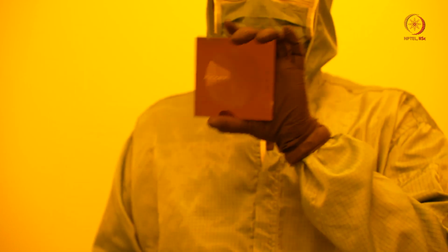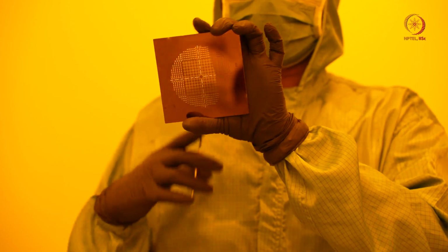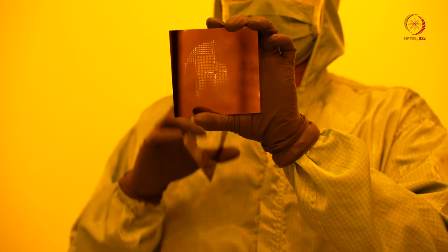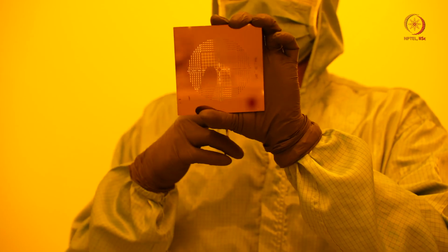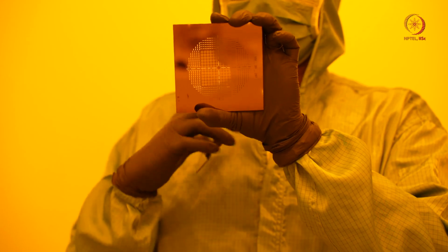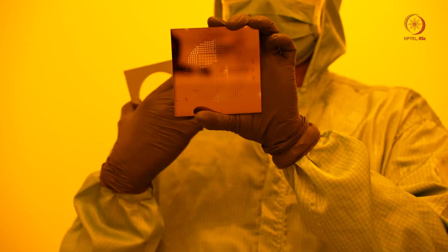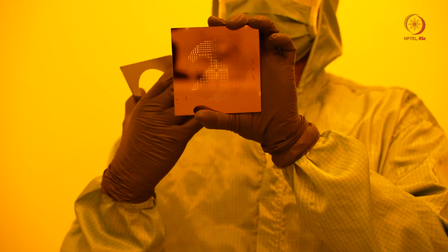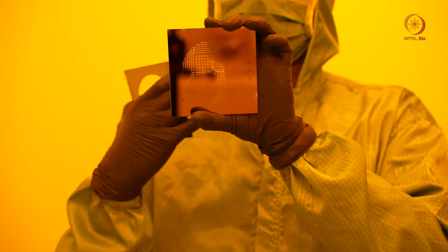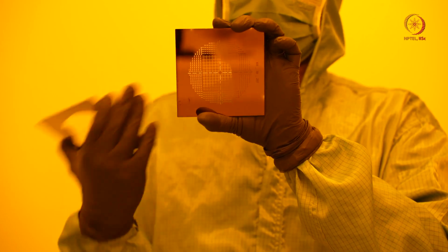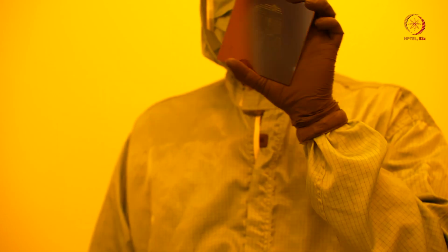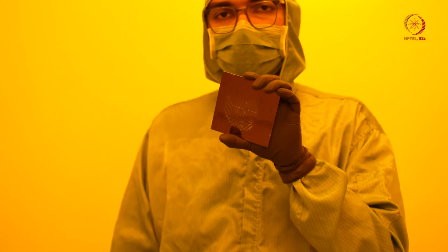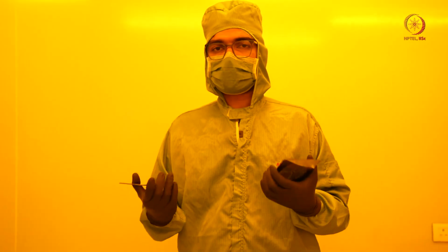Now if you look at a dark field mask, to get the same effect, what we have to use is a dark field mask coupled with a positive photoresist. Then what happens? The light passes through the pattern and falls on the positive photoresist, and wherever light is there, the photoresist becomes soft. So the pattern areas that we need will get the photoresist removed, and we can deposit metal. So in today's process we will be using this photo mask coupled with a positive photoresist, so as to get the lift off feature that we need.